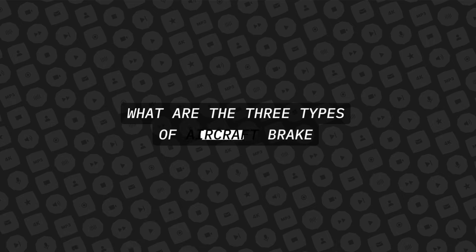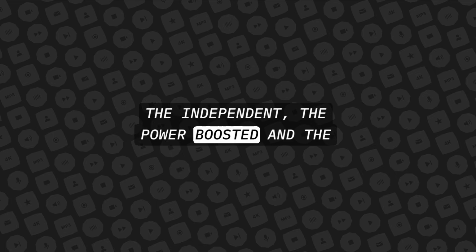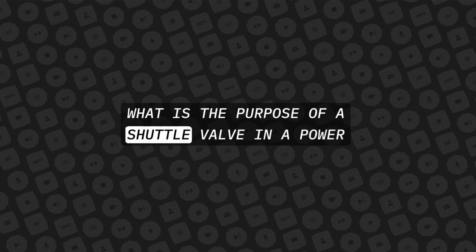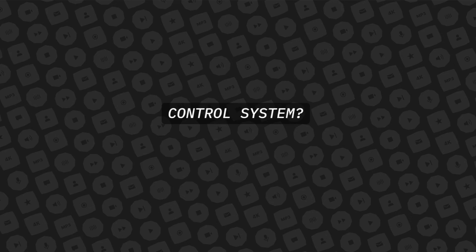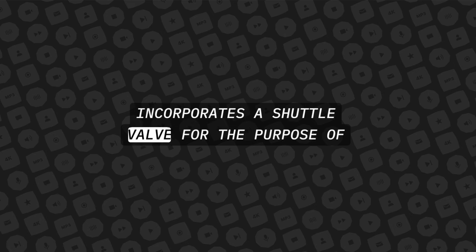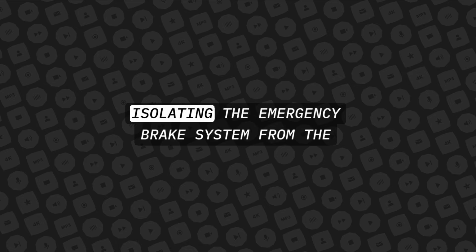What are the three types of aircraft brake systems? The independent, the power boosted, and the power control type. What is the purpose of a shuttle valve in a power control system? Each brake actuating line in a power brake system incorporates a shuttle valve for the purpose of isolating the emergency brake system from the normal brake system.